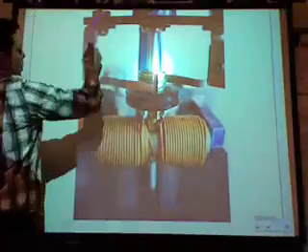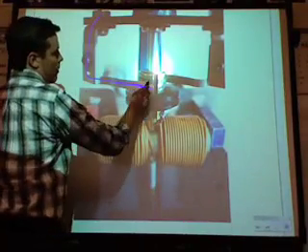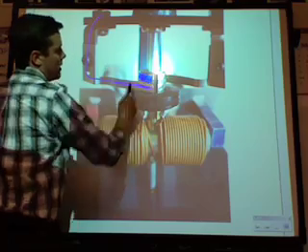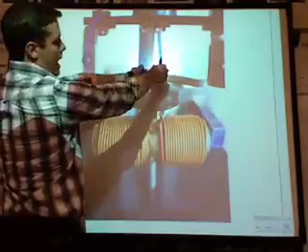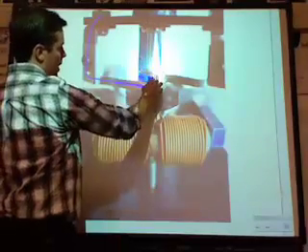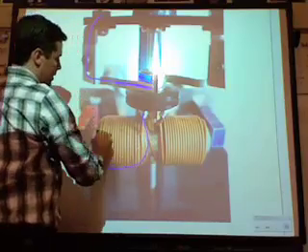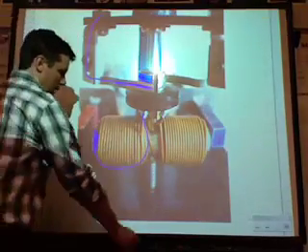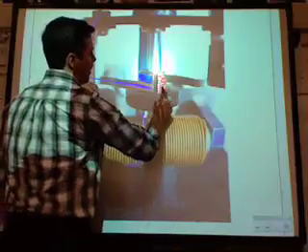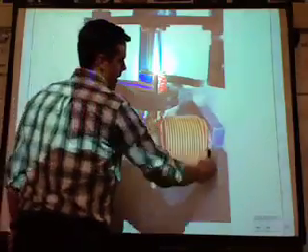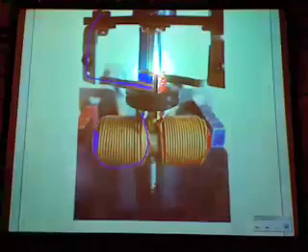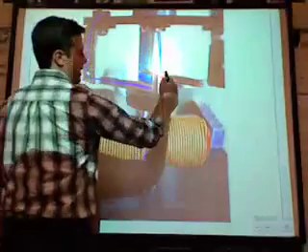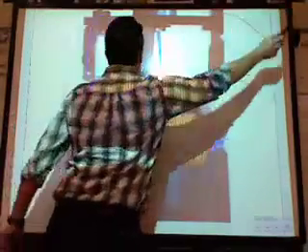In this picture, you can really get a view of how the switching is accomplished. Right now, if one wire comes down and connects to this flap, it's going to make a connection to this half of the ring. The ring has been split in half. One half of that ring comes down here and connects to this end of the coil. The other half of the ring, this part here, connects to this end of the coil. Notice that this flap here touches that half of the ring and goes off to a different wire.